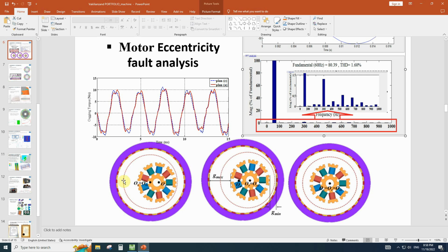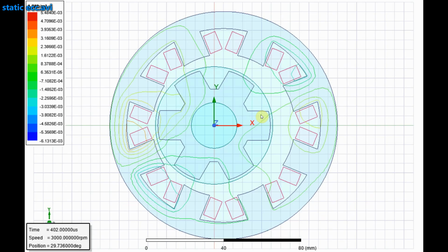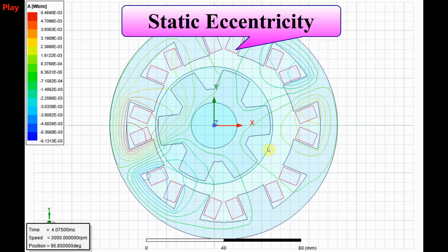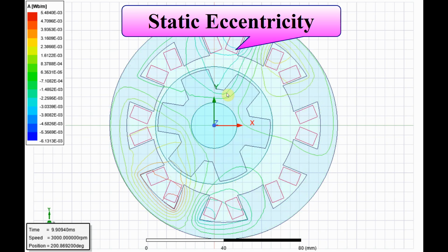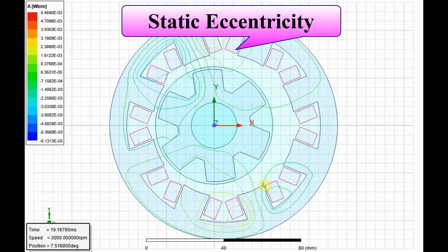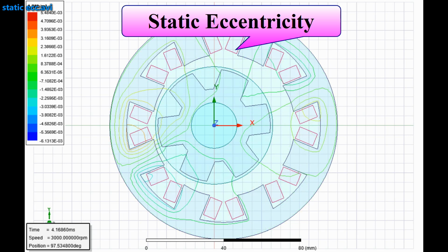To show these two faults better, I made a video of each one of them. It is an SRM motor with an exaggerated air gap. With a low air gap distance, we can't see what's happening there. But in this simulation, we will have a big air gap machine to understand the problem better. In this animation, you can see the static eccentricity. The rotation center is matched with the rotor center and the stator has displacement. Let's see it one more time.